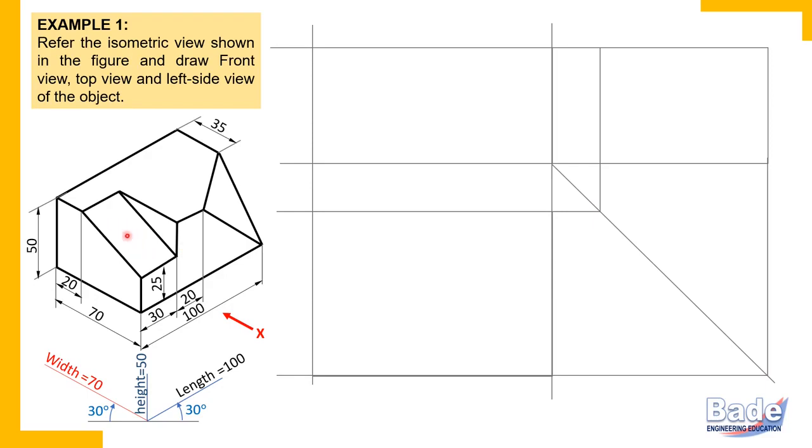Okay. Now, this surface is not a principal surface. It has a principal edge, one more principal edge, but these are parallel principal edges. This is a non-principal edge. So this surface does not have two principal edges which are perpendicular to each other. Same way, this is not a principal surface. This triangular surface is not a principal surface because it doesn't have two perpendicular principal edges. All these three edges of this triangular surface are non-principal edges.